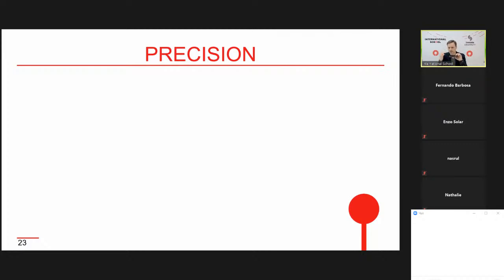But we cannot make it 7 millimeters because our world is not ideal, which means we will make it, for example, 6 millimeters 0.99 or 7 millimeters 0.01. And this range between minimum and maximum is called tolerance. And every part, every surface of part has its tolerance.